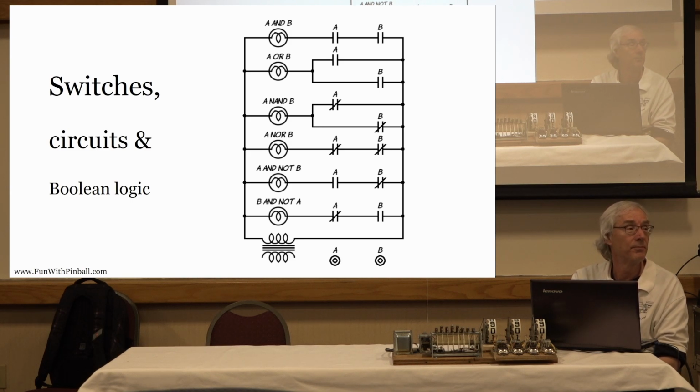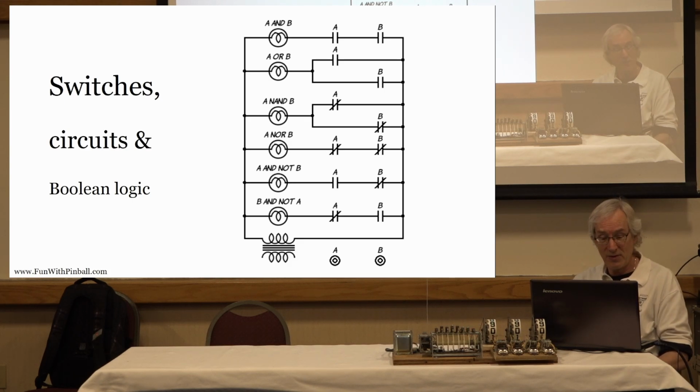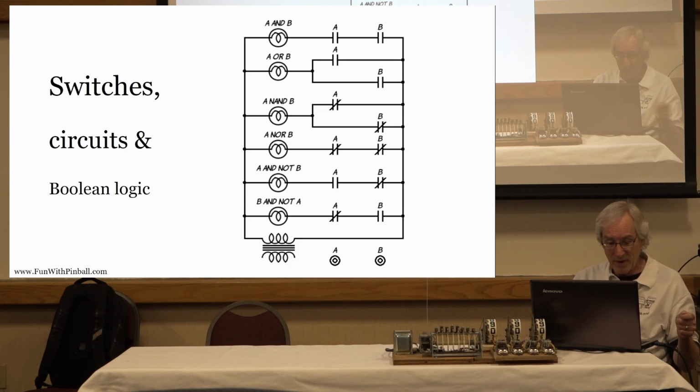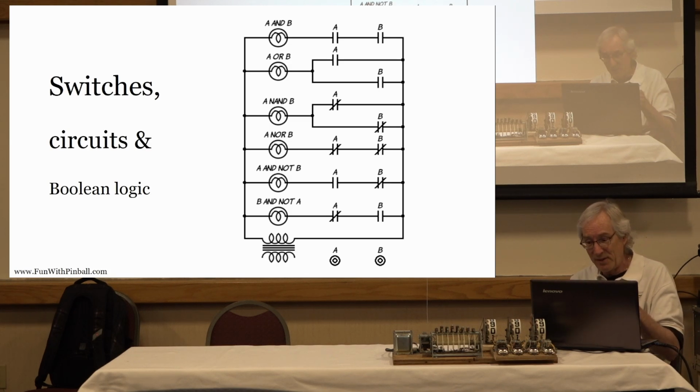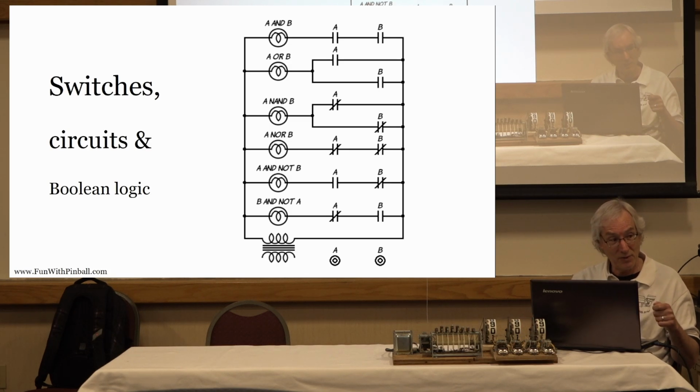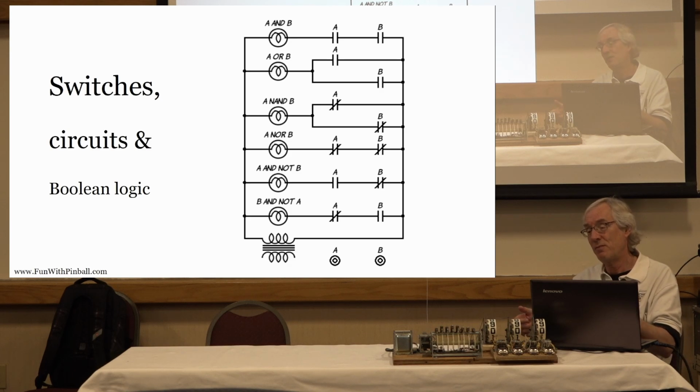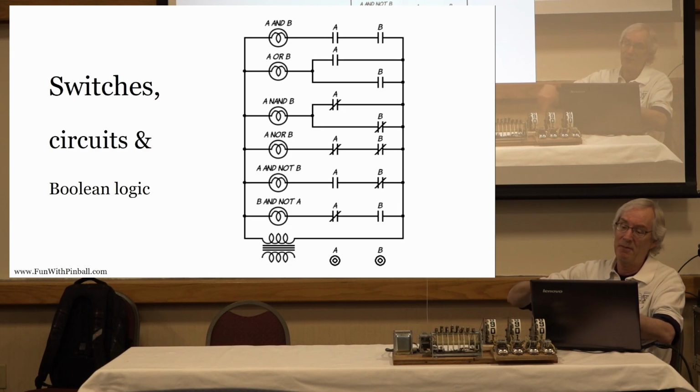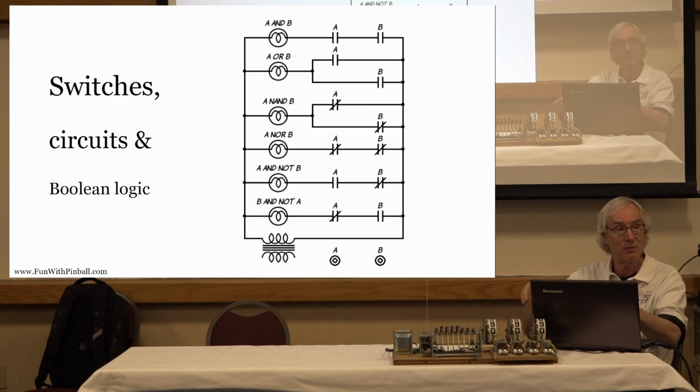Yeah. When you're troubleshooting, is there a tool you can use to send current through a part of the circuit, like you just touch it? Yeah, absolutely. So if you have a jumper wire, which is a piece of wire with alligator clips on either end, I can jump in there. If I suspect that this switch isn't closing, I could jump to either side of that switch and provide a bypass around that suspected switch.